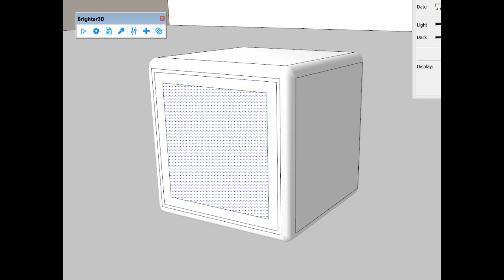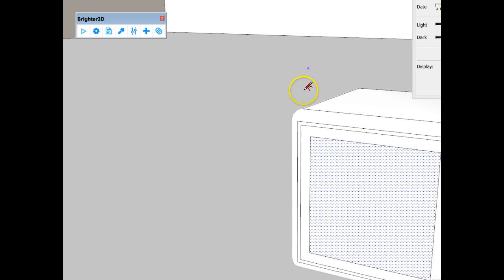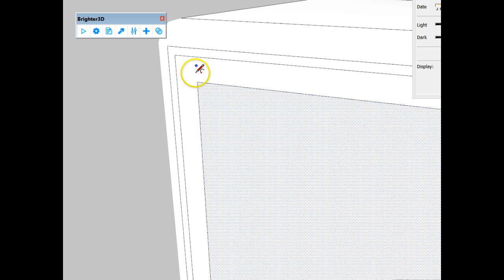So I'm going to click on here. If I zoom in close, you'll see I'm just going to use that as a reference point. I click once, go to my second point. Sorry, I actually must have clicked on that first. Click once, go to my other side, and double click, and you see it removed the corner for me. So there's no need for guidelines. I'm recording here, so it's a wee bit jumpy.